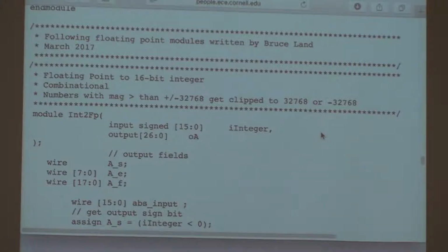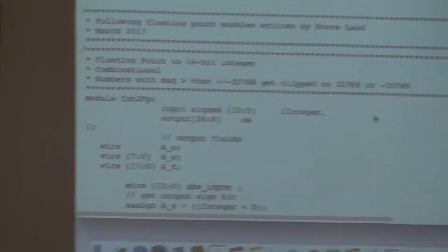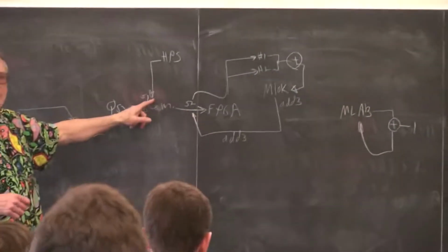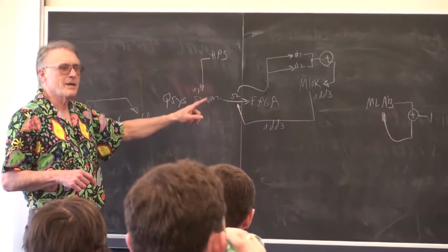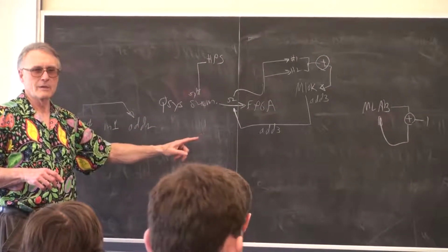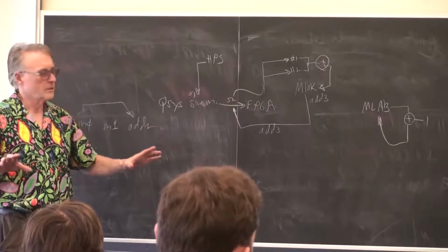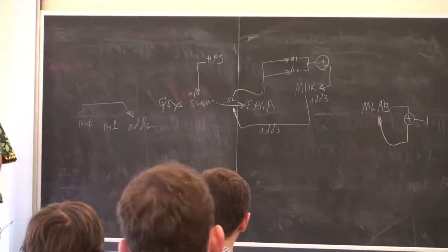These are all full speed reads and writes, so I don't think I was taking any shortcuts. The only possible shortcut is that the other port of this port's running at 100 megahertz, this one's running at 50. So depending on exactly how the core works here, maybe I didn't have to put a wait cycle in. I'm not sure. But it's a safe thing to do: put in a wait cycle after you write.